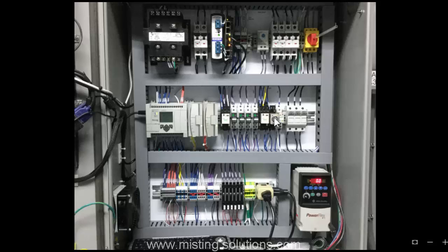It plays somewhat of a critical part of the operation of this unit, and it is only energized when the system shuts down. Now, I don't mean when the system shuts off. What I mean is when the system quits calling for humidification, gets to that point where the JCI controller says, I don't need any humidity anymore. So it's a 3-second timer, and as soon as the system quits calling for humidity, a set of contacts close for 3 seconds, and then they open back up again.